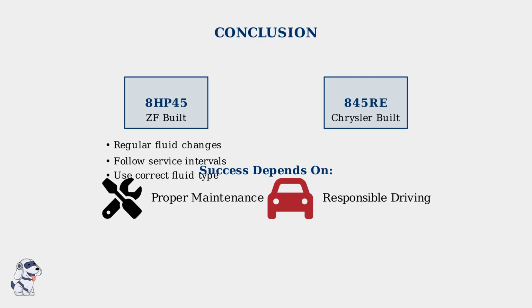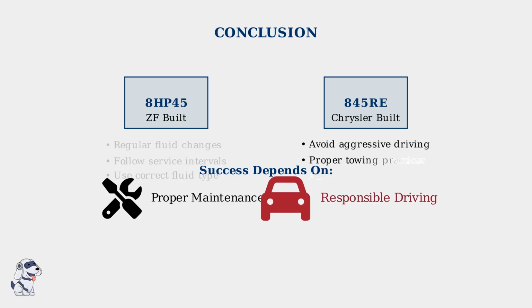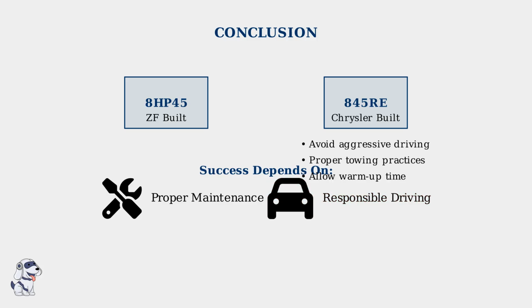Proper maintenance includes regular fluid changes with the correct transmission fluid, following manufacturer service intervals, and addressing any issues promptly. The transmission fluid is truly the lifeblood of these complex systems. Responsible driving means avoiding aggressive acceleration and braking, using proper towing techniques when hauling heavy loads, and allowing the transmission to warm up properly in cold weather. These habits significantly extend transmission life, regardless of which version you have.